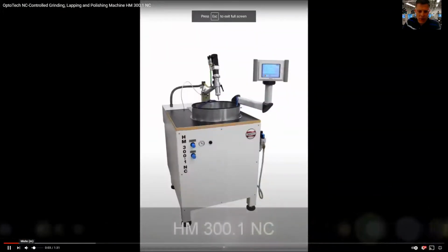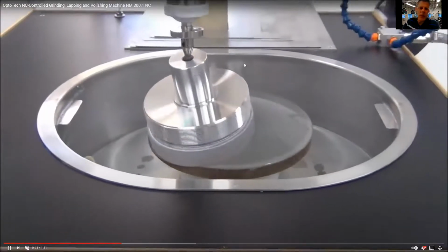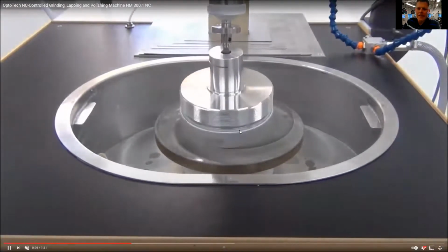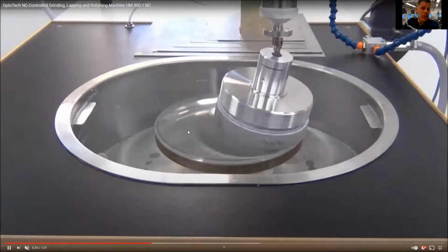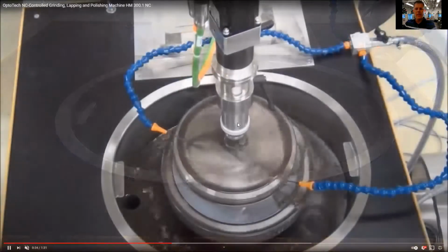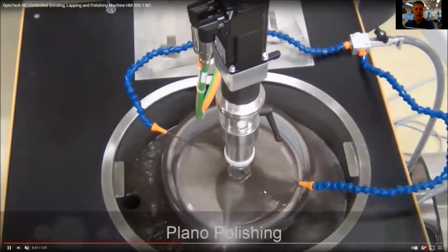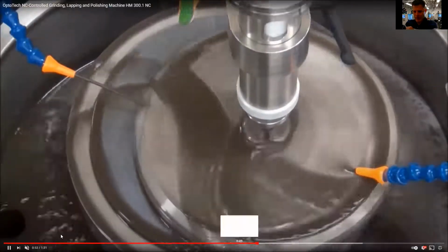glass. So I mentioned it, you could do it on curved surfaces as well, right? So now they're plano poly, they're lapping a glass lens. So after you maybe cut it to the right shape using your ultrasonic machining non-traditional process, you might want to lap it to go ahead and get it basically polished or nice and clear. So they said we got some nice,